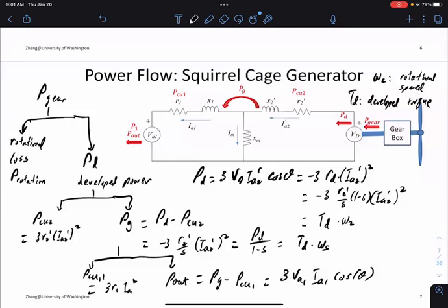So the power factor of this generator will not be great. Power factor is normally in the 0.4 range, so it's very far away from unity power factor, but that's not something we can deal with yet. In this case, we don't have an excitation system in this type of turbine, right? Yeah, we don't have excitation here yet. There's no excitation, so there's nothing we can control for reactive power.